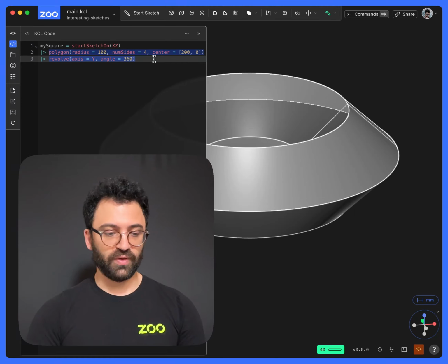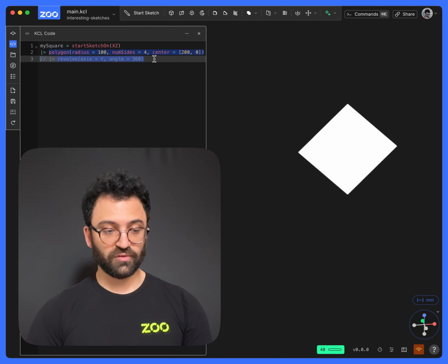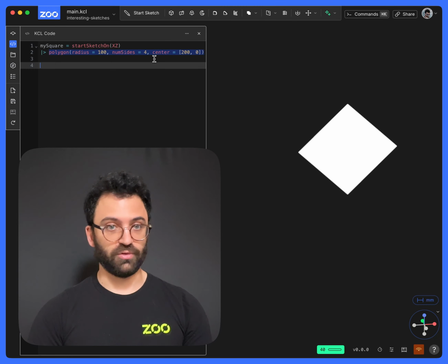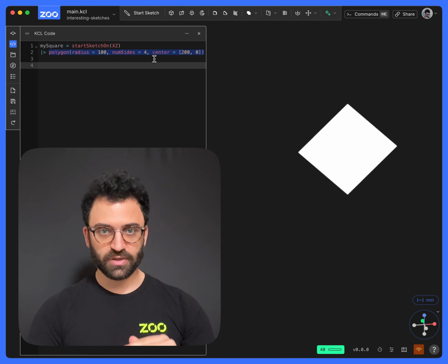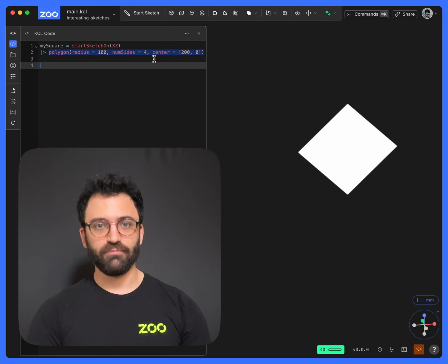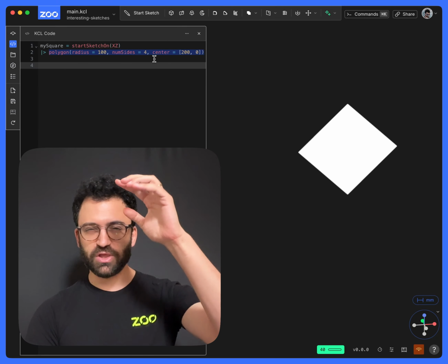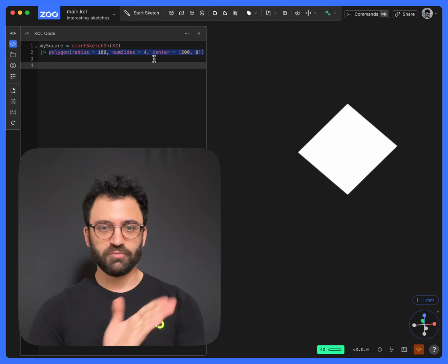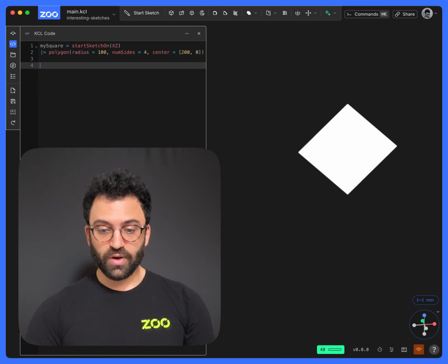The last one I want to look at is called lofting. All the previous calls we looked at, where you had a sweep, or an extrude, or a revolve, they all took a single flat 2D sketch and made it into 3D. Lofting is a little bit different. With lofting, we take multiple 2D shapes and join them together. We make a new interesting 3D shape that smoothly goes from one 2D shape into the next one. So let's take a look.